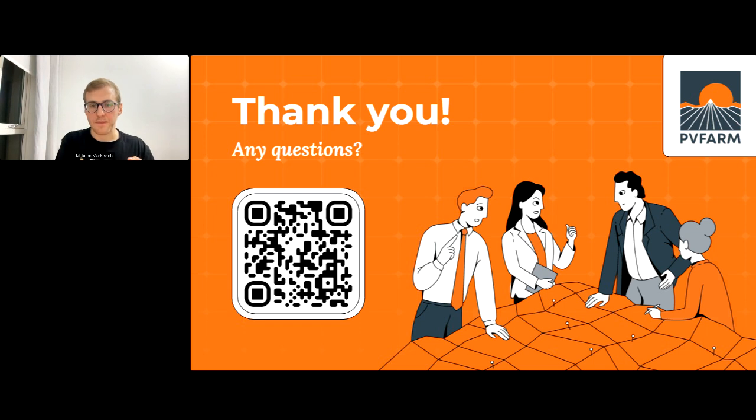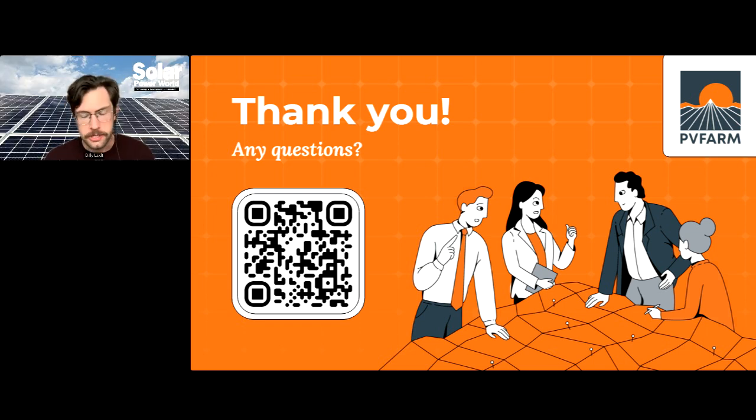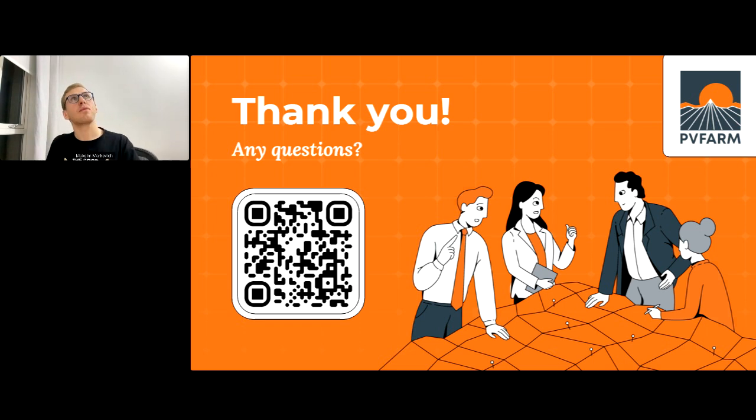Got it. All right. Next up, what is the best way to get tracker configurations? I would say it depends on what's needed, but I would start from electrical configuration: modules, number of modules, number of strings. Then I would check the length, whether it's satisfying for me or not. If not, I would start tweaking gaps, motor gaps, module gaps, and overhangs until I achieve the required length of the tracker. And only after that, I would start working with piles.